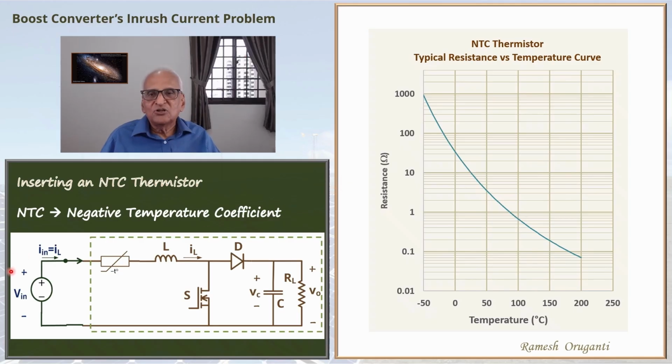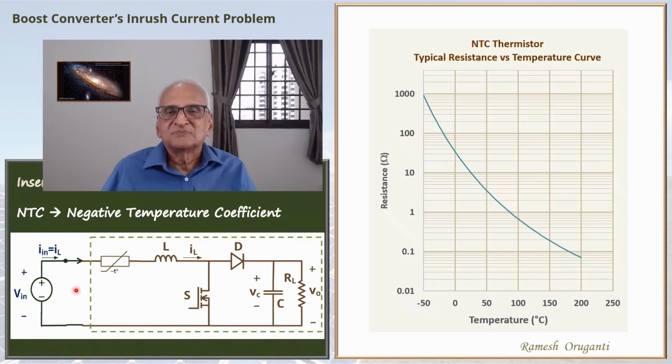If you turn on and turn off this switch too often and do not allow the thermistor time to cool, it may be a minute, then you may not be giving sufficient time for the thermistor to cool, and so a surge of current may still happen and a fuse may still blow. Otherwise, this is a popular solution used in phone chargers, laptop chargers, etc.